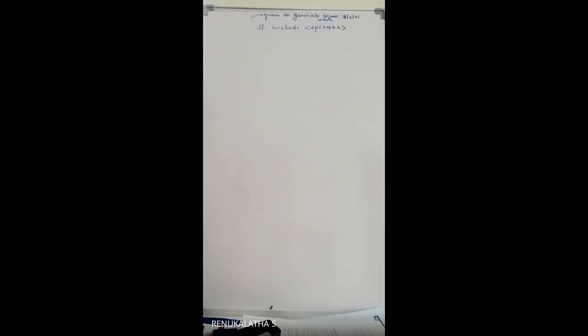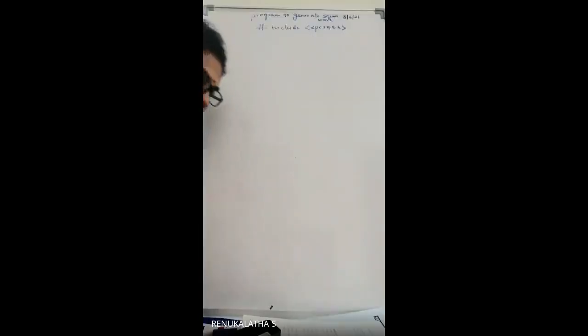What is the data that should be sent to the DAC? What data do you need to send? Come on, answer. We should send ones and zeros, ma'am. Ones and zeros you have to send, right? So now, you have to use the IO pin register, IO0 PIN register. Okay, what should be its value? IO0 PIN register is a value register.